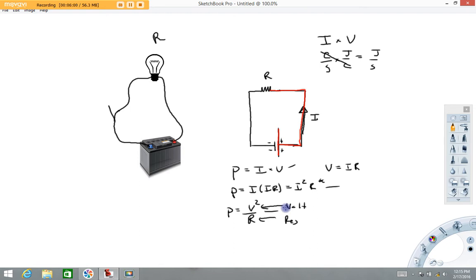There's a very important fundamental, though, that I want to point out right now. Actually, two important fundamentals. Important fundamental number one: you'll notice that power is very sensitive to current. If I hold resistance constant, but I double the current, there's 4 times the power output. And what that typically means, as far as electrical circuits are concerned, is a lot of heat loss. As a rule of thumb, it's not very advantageous to run circuits at high currents because there's a lot of heat.